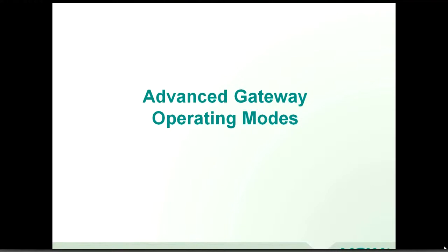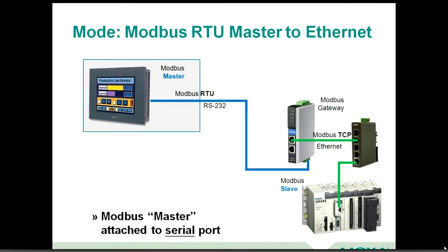Some of you folks mentioned that you'd actually done some applications with gateways, so let's take a look at some of those. Now, we used the example of having the Modbus RTU devices only on the serial side. You can actually use these in a reverse configuration, and it looks like this. If you've got an HMI and the HMI only talks Modbus on serial, you can use this in a backwards configuration where you have that HMI pull data from an Ethernet connected PLC. Pretty useful way, and again, all you need to do is go into the mode settings and change that within your gateway.